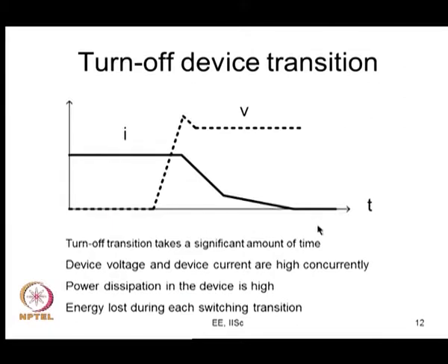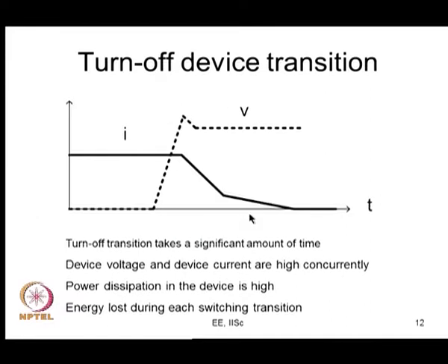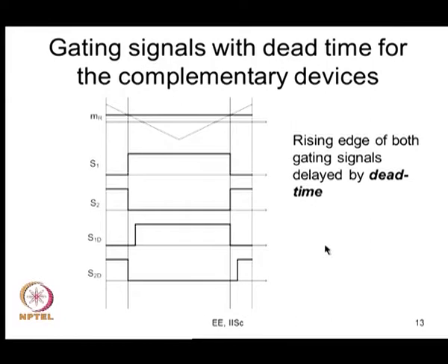This time can vary with the voltage level, the current level, the ambient or junction temperature and so forth. It can vary because of certain parasitics in the circuit. So, you can take no chances, you have to allow for some time which is much longer than this switching interval, and only after that time should you turn on the next device, as shown here. So, that is the idea of our dead time.